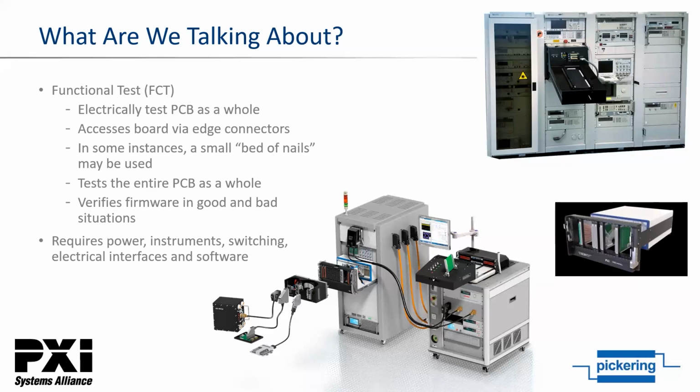The advantage here is that we're testing the unit as a whole, just as it would operate in the real world, and can verify firmware in known good and known bad situations. In virtually every case, the test system will integrate power supplies, instruments, switching, electrical interfaces, and software that operates the tests, makes appropriate measurements, and determines the pass-fail status of the unit.